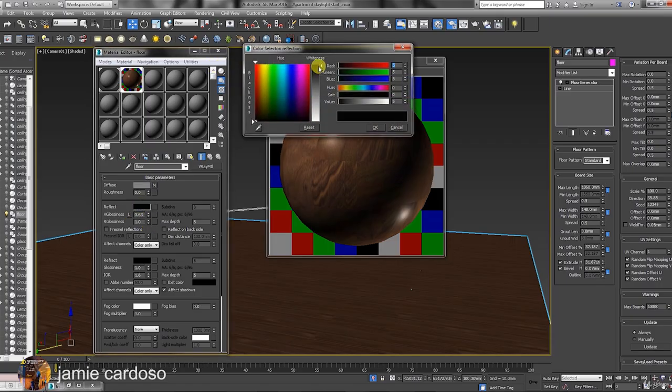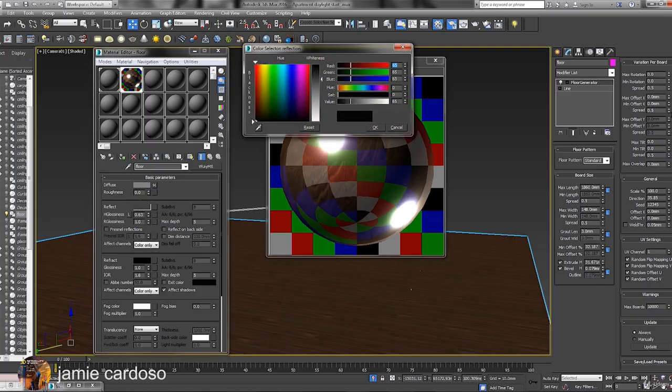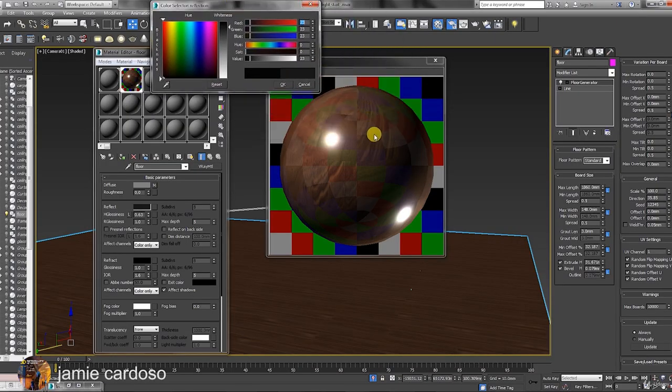Click and hold the color swatch to bring up the color selector dialog. As you move the slider values to a brighter tone, you can clearly start seeing the reflection amount being displayed as checkers in a floating material preview. As you can see from the checkers material preview, the current reflectivity looks too linear. To disperse or diffuse the reflection slightly, simply reduce the reflection glossiness values.